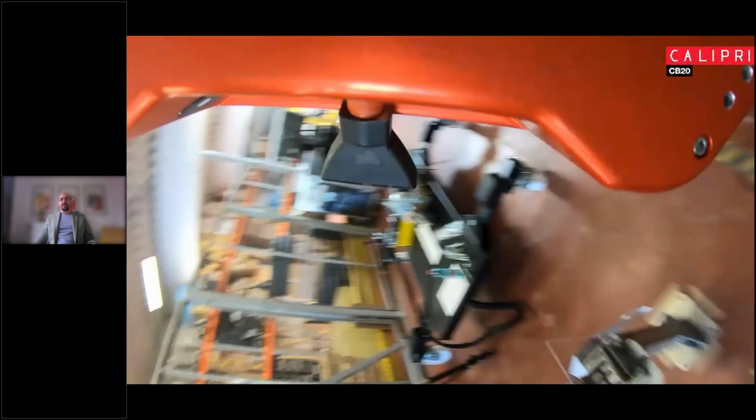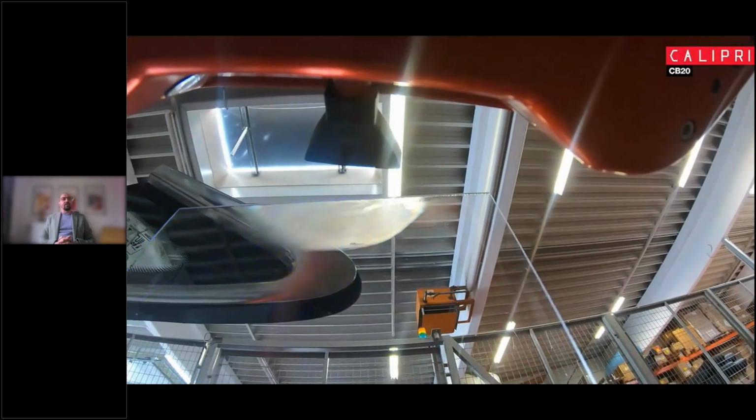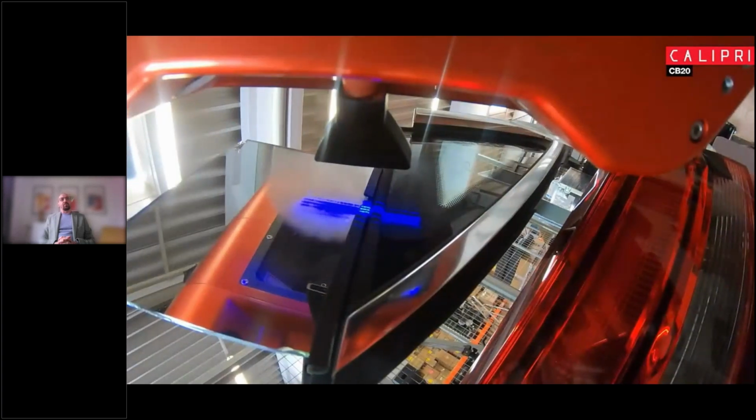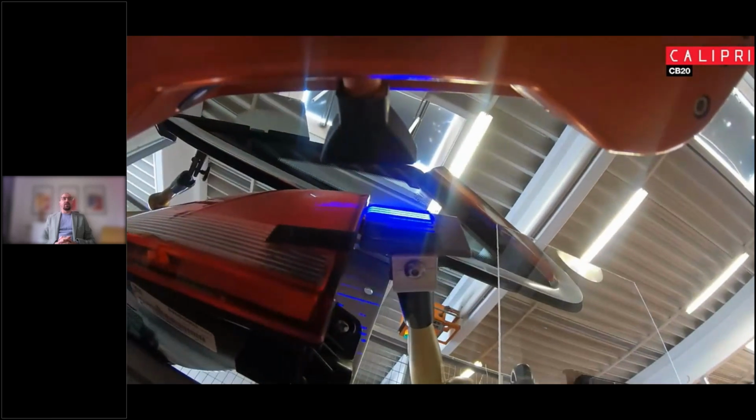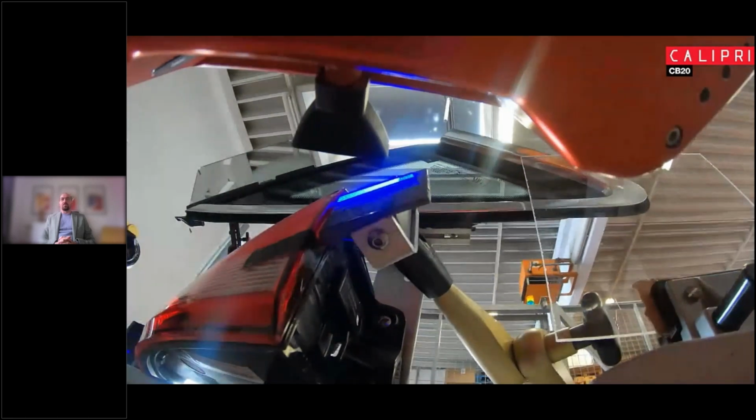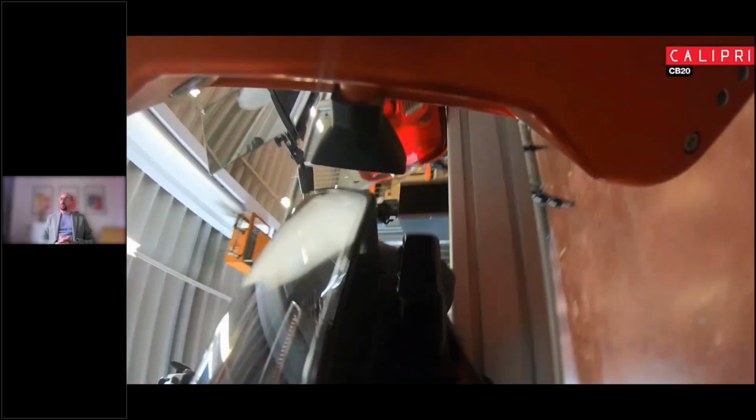So here is a little insight into our production facilities. You can see the nozzle breathing on the transparent surface. We create a fog layer, a condensation layer, which will disappear. So there will be no residues as we are using distilled water. So we can always measure on the customer car. We make sure to be able to measure each and every surface, sorry, to measure on the most outermost layer every time and to be repeatable. So we have a solution for problem number 1, the transparent surfaces on a finished vehicle.